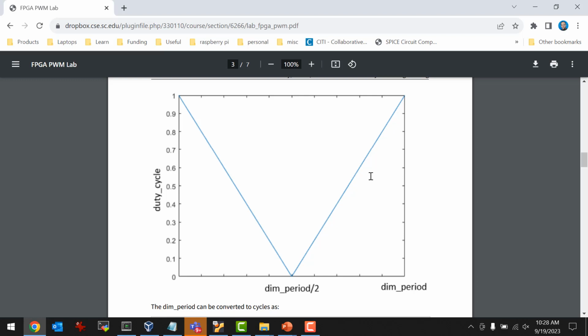You have to be able to toggle that PWM signal. The whole period may only be at 100 kilohertz. You only have 10 microseconds for your period, right? But then the duty cycle is a smaller portion of that 10 microseconds. So if your duty cycle is, say, 20%, you're now having to operate on a time scale that's 20% of 10 microseconds, so 2 microseconds. That makes sense? That's not a lot of time for the processor to get its act together, right? So that's a fast signal.